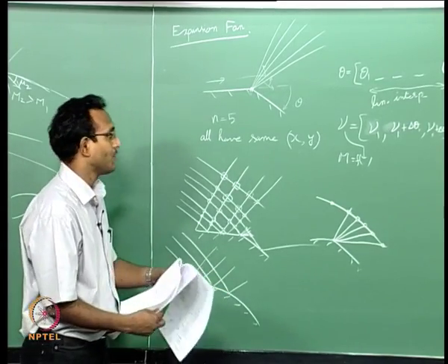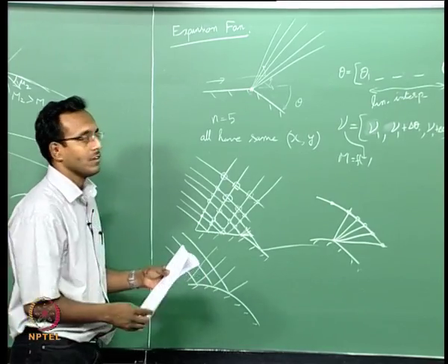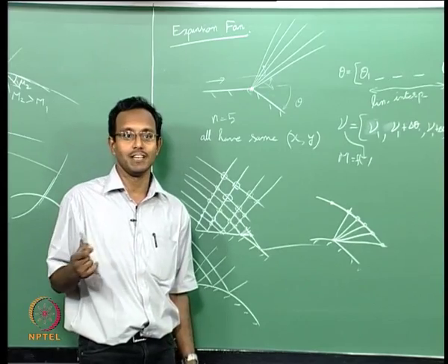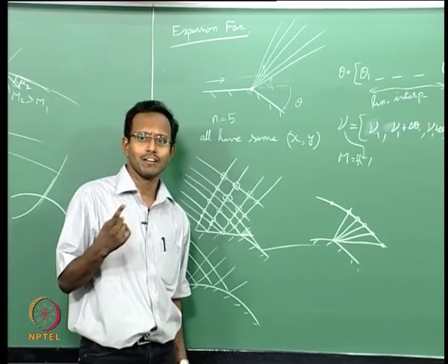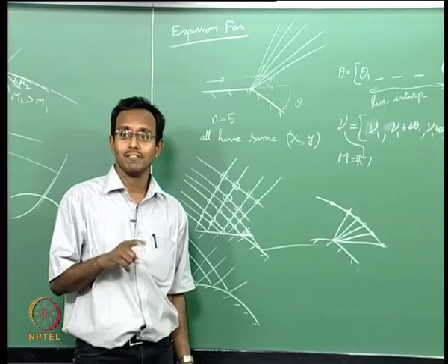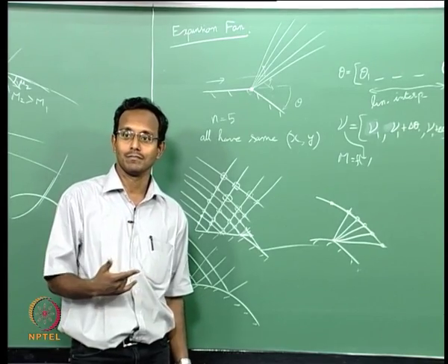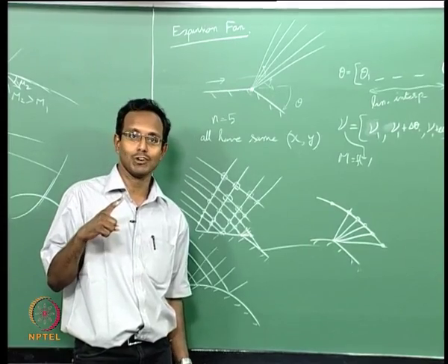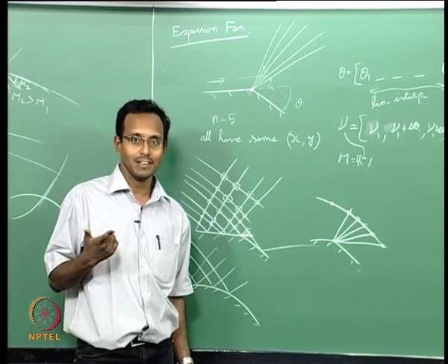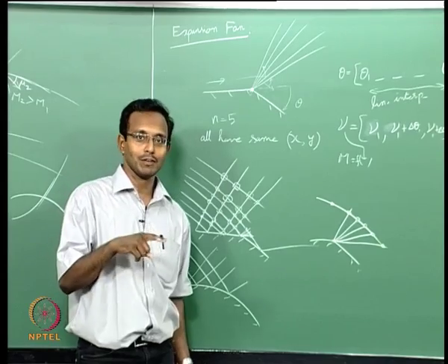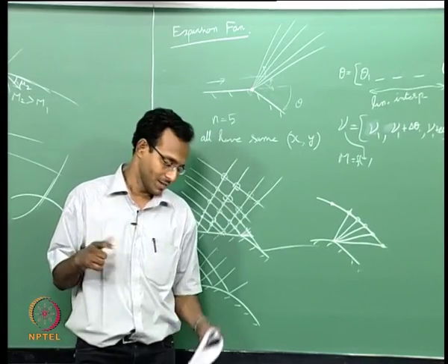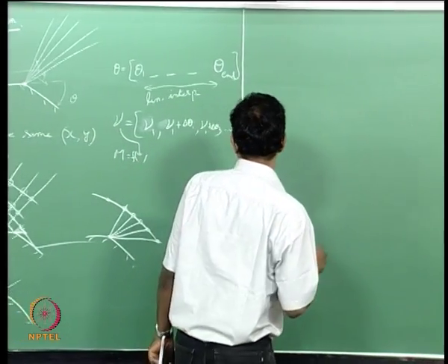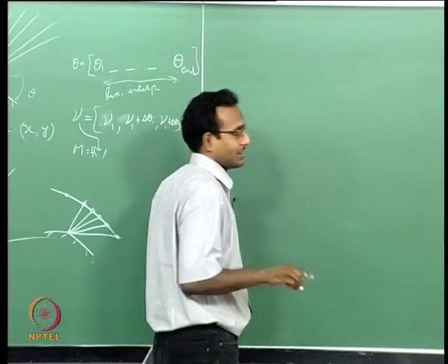Okay. As of now, we are at a point where we can solve some standard problems without any shocks in our flow. If there is a shock and there is subsonic flow behind the shock, we cannot solve it beyond that point. But if it stays supersonic, say a weak oblique shock, then definitely I can solve it. Okay. That is still a special case.